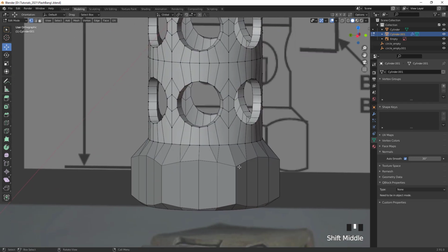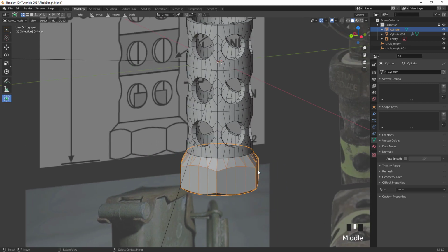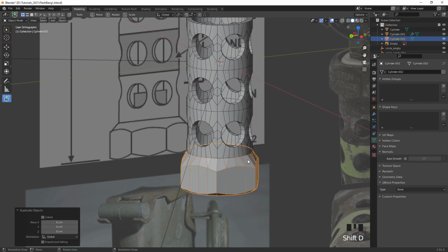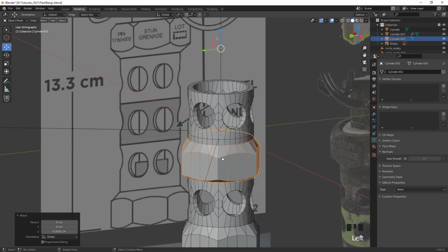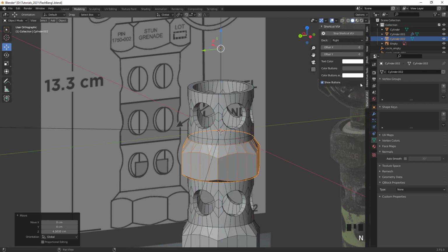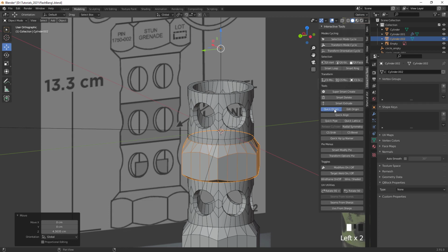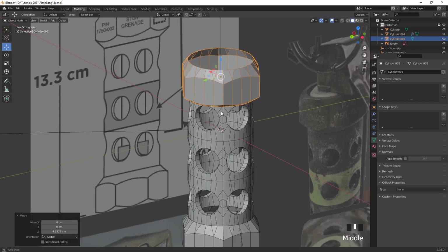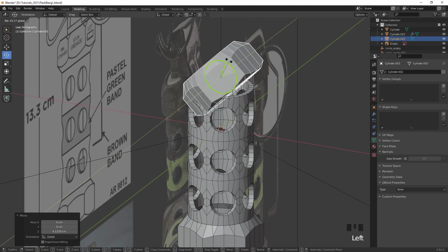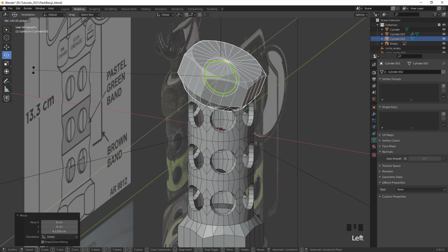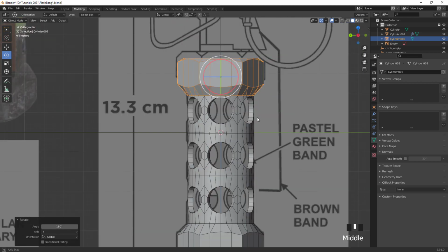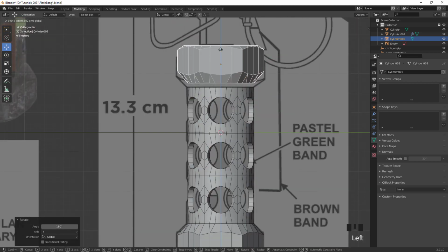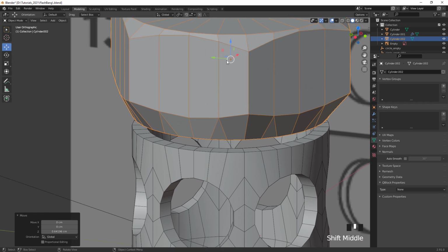So next, I'm gonna have this element here, and I wanna make a copy of it, Shift D, and then I'm gonna bring it up here. I'm actually gonna put the pivot to the center here. When we go to the interactive tools, you can make a quick origin that centers our pivot. And then what I'm gonna do is go over to rotate, and then we're gonna snap it with the control button pressed so that we have a 5-degree snap, and that way it's perfectly 180-degree rotated.